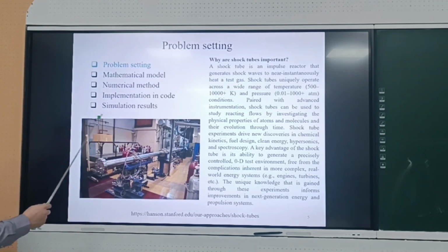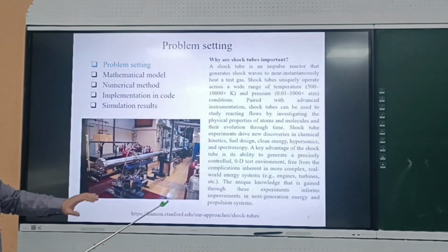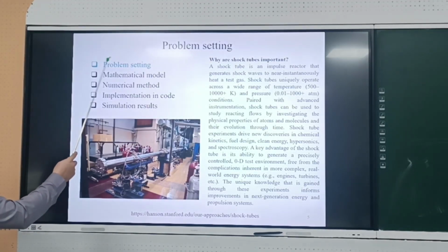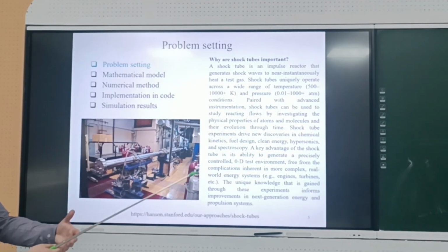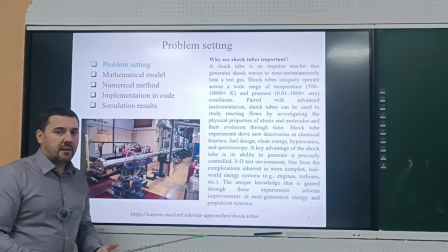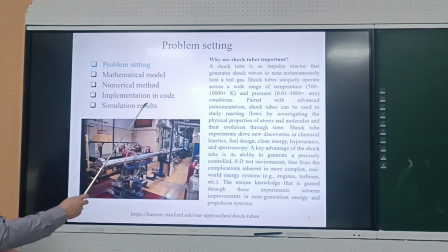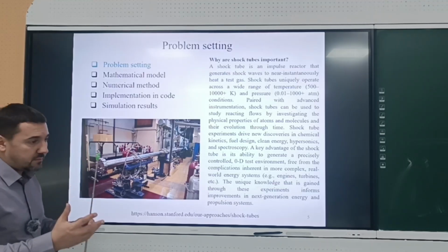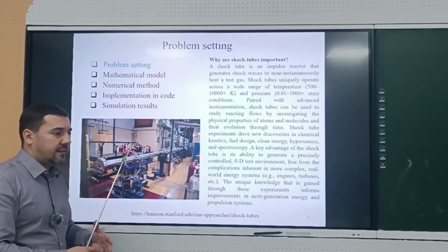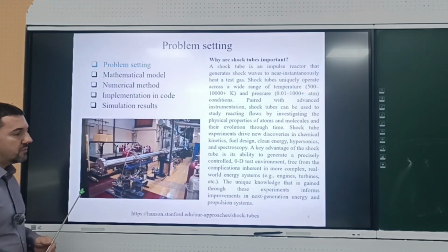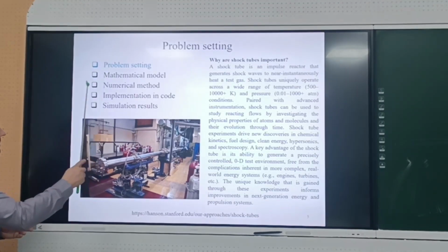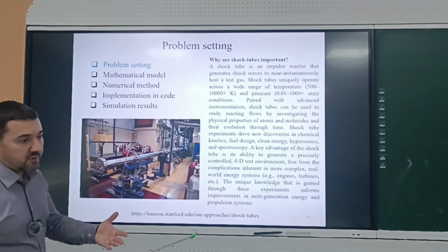And we discussed in the first lecture there are typical stages of the process of numerical solution of any problem. So first of all, we should define what is called the physical statement of the problem. At the physical level we should understand what problem we would like to solve. Then we should define a mathematical model. So we should build the geometry of our object if it's multi-D, and then we should define the mathematical model. Mathematical model means that we should choose the defining system of equations, partial differential equations in our case. Then we should define and choose the numerical methods, suitable numerical methods.